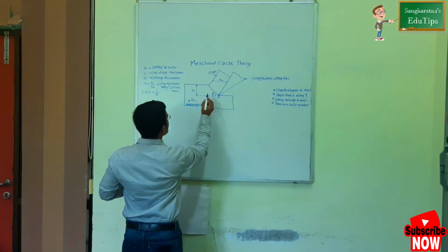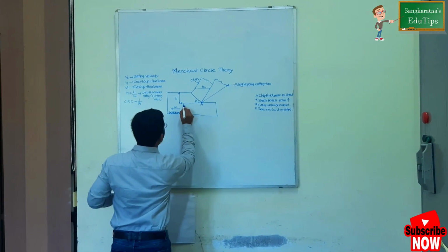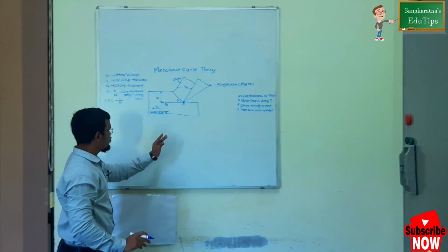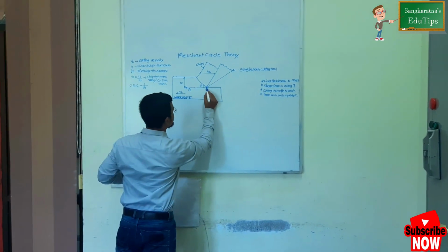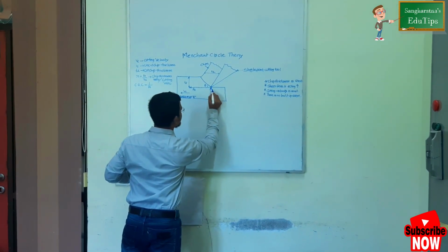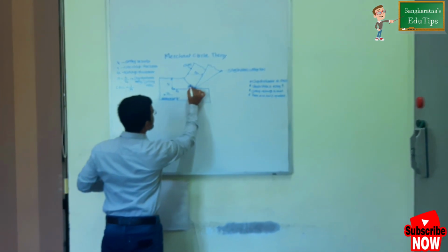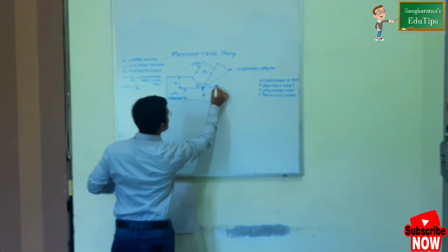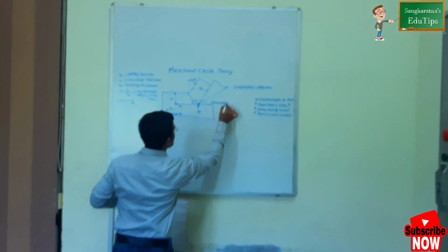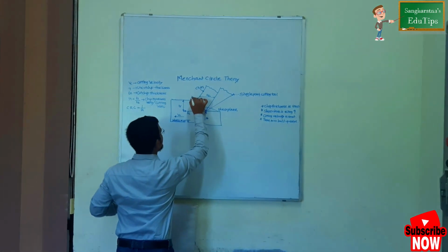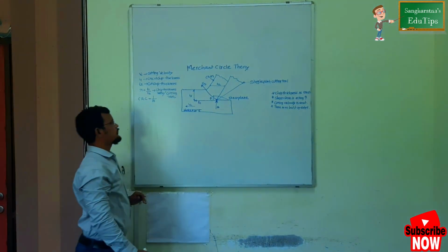Along with this, the forces are generated. This force is nothing but the cutting force, which is in the horizontal direction. Perpendicular to this cutting force, there will be the thrust force at this particular point, denoted by Ft. Along with this is the shear plane, along which the material will be removed, and the force acting along this direction is denoted by Fs, that is the shear force.